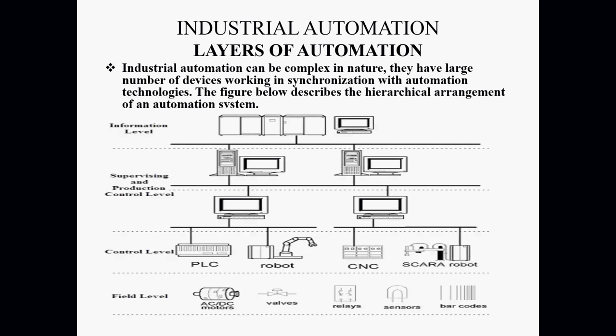So what you do is you integrate the data from all the different control systems, get this to your server where you're going to archive this, and use software solutions such as Historian and reporting MES solutions to create meaningful reports out of this data, right? So that you can get a complete overview of how much your production was.